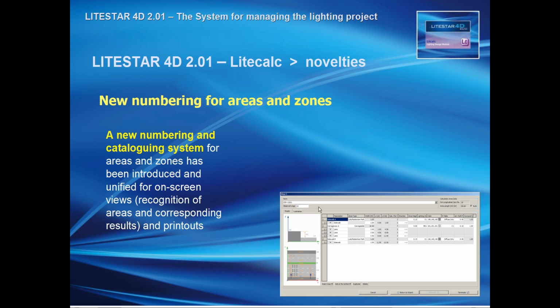You can see here, for example, what's appearing at the monitor when you work with the advanced module for roads, for road lighting. In here we have the zone. So in this case, this is the first zone introduced, which is the zone close to the x-axis, and close to the origin. Then we have a subzone, which is named 1.1. If we have different subzones belonging to the same zone, it will be 2.1, 2.2, 2.3. This way of numbering is common to the monitor, is common to the results view, and is common to the printouts.